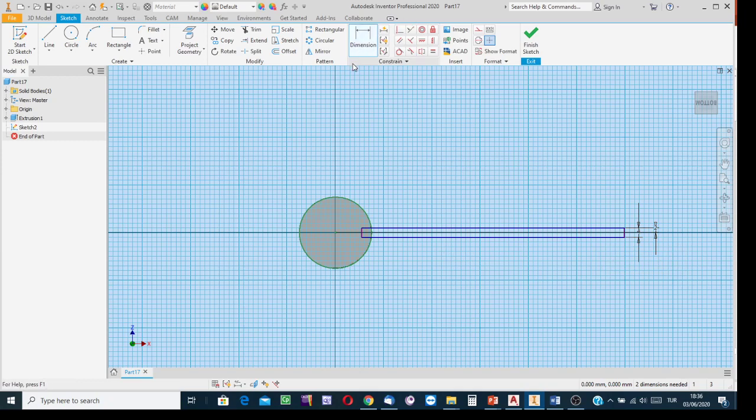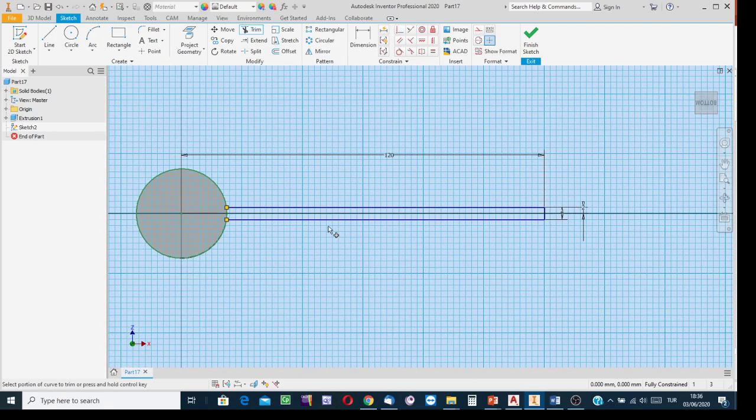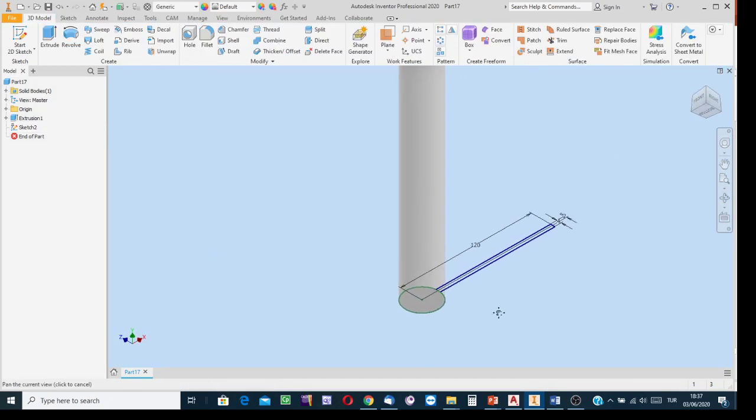Depending on the volumetric flow rate, and of course it depends on the speed of rotation, say that the designer determined the height of the thread from the center is 120 in this example. No need to have these further extensions, trim. And then yes, this is the profile. Repeat again, this profile is the base of the helical groove at the beginning of the rotor or at the end, depending on the point of view.